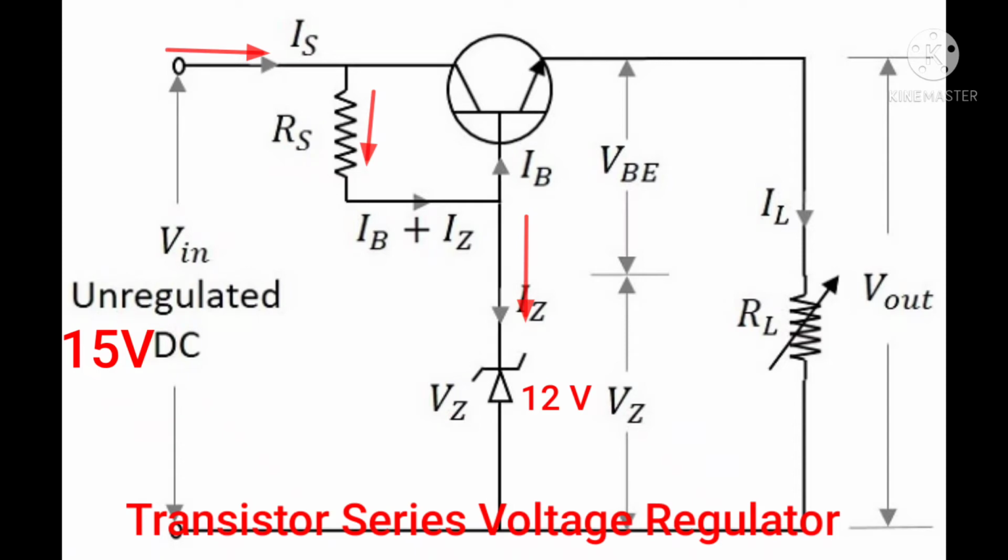The output voltage is maintained by the zener voltage, which is constant, as both of them are maintained equal. Any change in the input signal indicates a change in the emitter-base voltage and output voltage. Both regulators maintain constant output voltages despite any fluctuation in the applied input voltage or variations in current drawn by the load. This is a fixed positive voltage regulator.